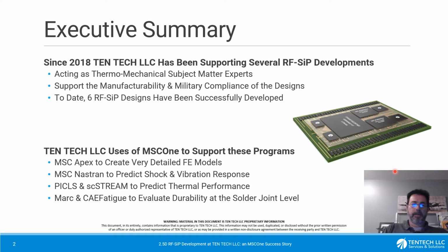that comes with MSC One. It starts early on with Pics for thermal validation of initial conceptual designs, to MSC Apex to create detailed models for further analysis, being shock and vibration, or MSC Marc and CAEFatigue for more complex analysis, including BGA, so solder joint fatigue analysis and strain calculations.